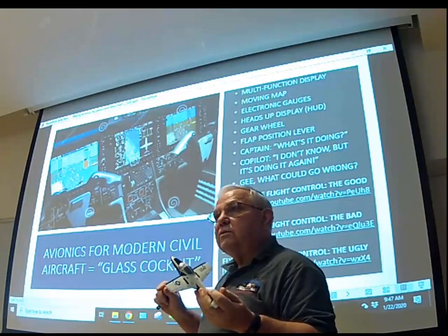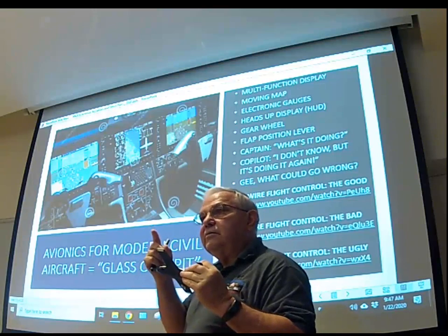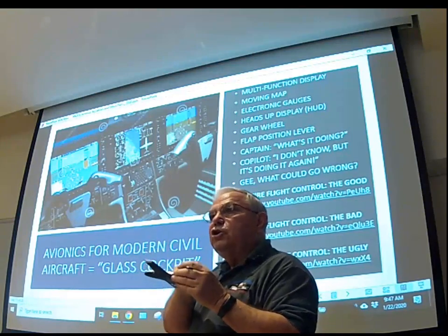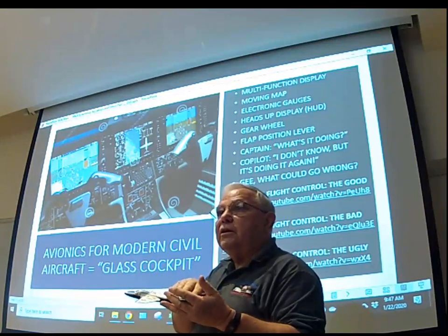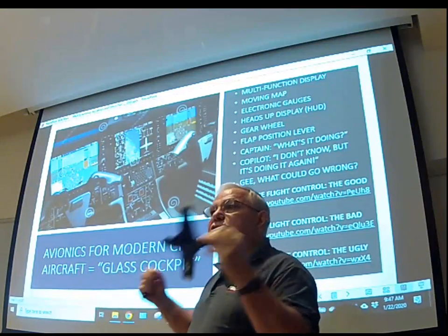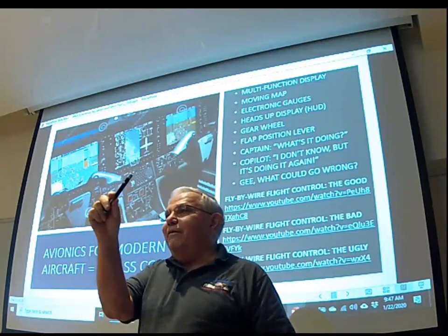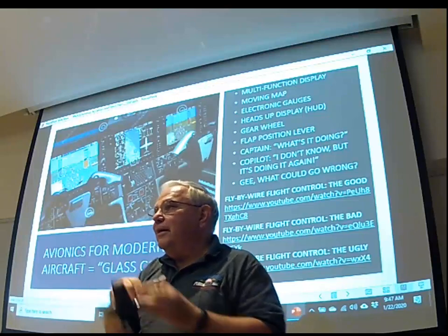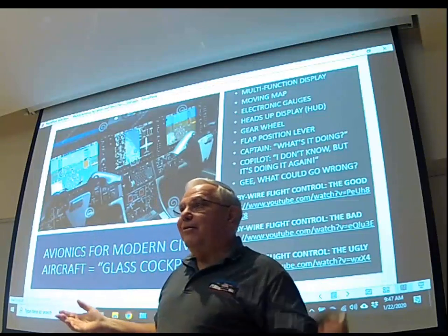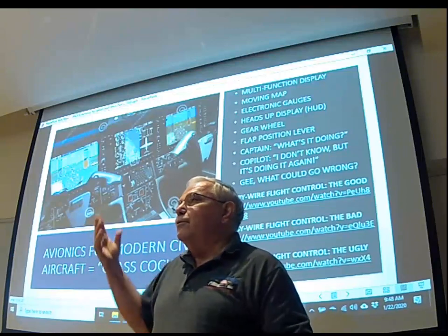But if you don't, as you saw in those examples, what happens? Remember the hydraulic system? These are huge controls on these fighters and airliners. They're huge. The space shuttle, they're huge. So you're using all the hydraulic pressure. If you watch the hydraulic pressure, it would go like this, woo, it's zero. But what happens when the hydraulic pressure goes to zero? And you're doing this in the cockpit? Nothing. There's nothing moving the control surface. The pressure is zero. You've got to wait for it to build up.